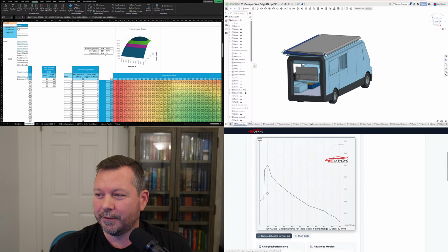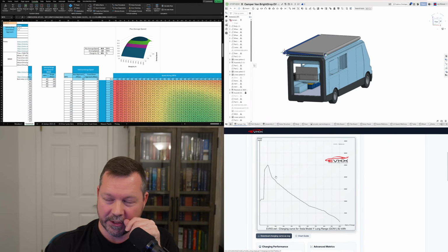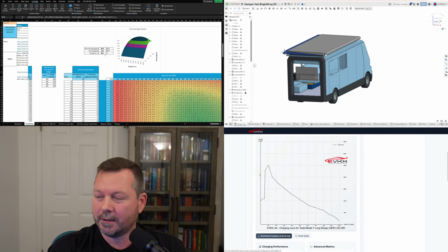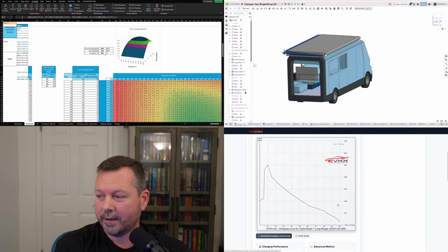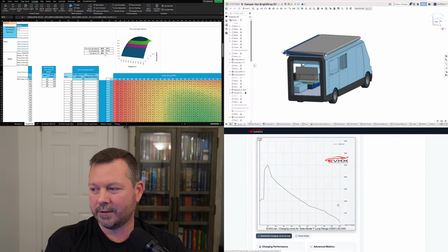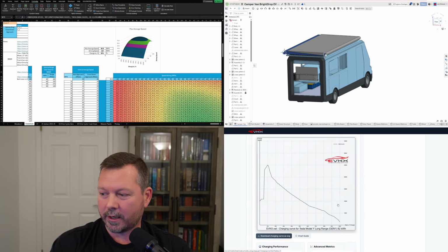So here's a charging curve, and it does just like this. You plug in, it jumps up to 250 kilowatt, and it's awesome. And then a few seconds later, it's already tapering off, and it just tanks all the way down. It does not sustain a good charge for a long time at all. So that's why on this one, optimal is only, say, 50%, because after that, you're down less than 100 kilowatt. And in the winter, I've been driving, I don't even get 100 kilowatt at 50%. It's dropping below that already.